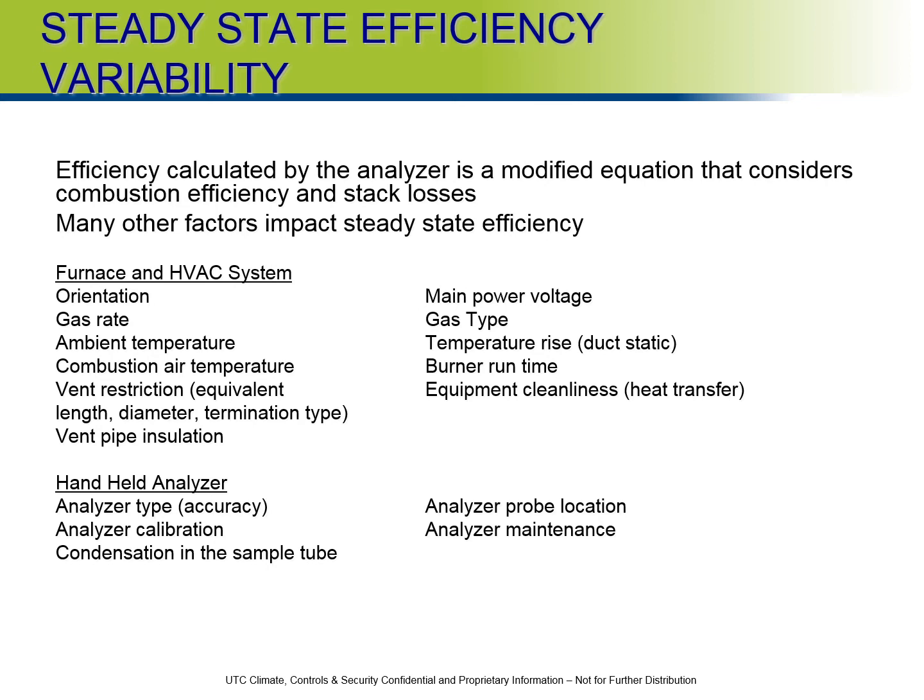Are we getting proper airflow through the system? That directly correlates to duct static pressure. As we all know, an increase in duct static pressure leads to a fall off in airflow, unless you're specifically dealing with a variable speed blower. Some of the other things that impact efficiency: like we said before, these pieces of equipment have to reach what we call steady state, which is typically after about 10 to 15 minutes of runtime. So burner runtime directly impacts it.